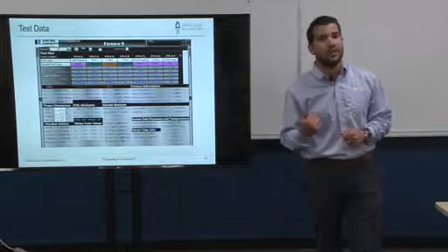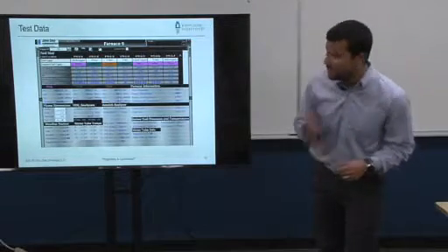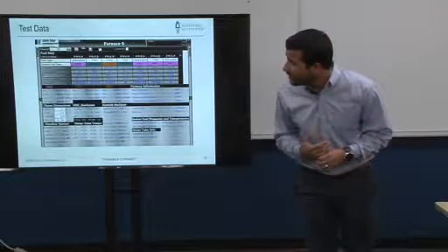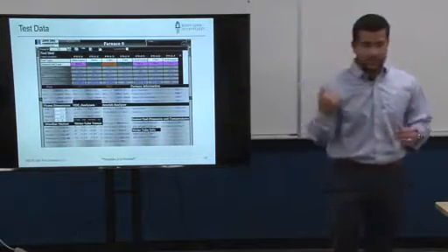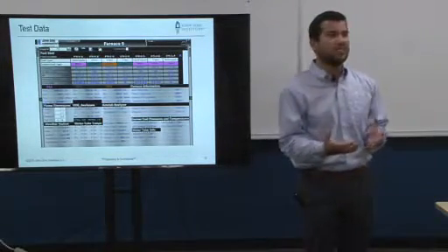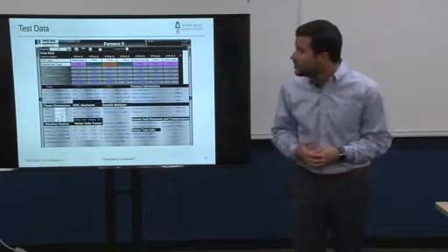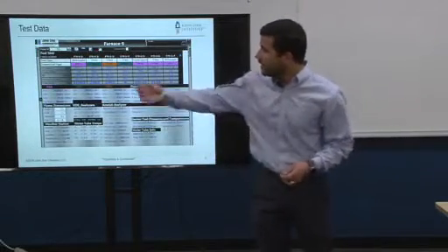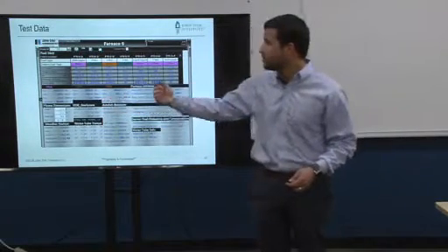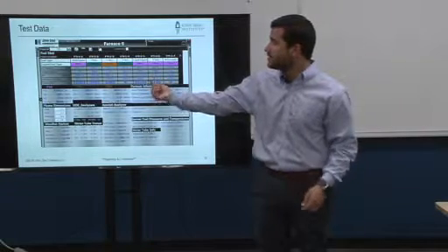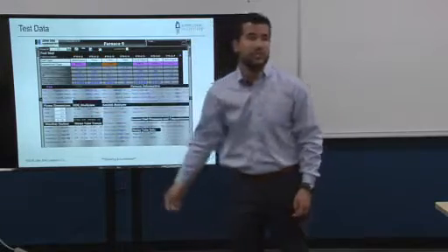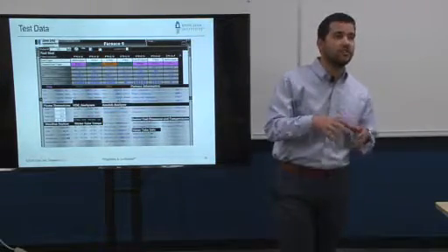So this is, I'm pretty sure I did this test. This is a downfire reformer, and actually using turbine exhaust gas too. So it's a downfire reformer where you have a main fuel that is your RFG, which stands for refinery fuel gas, okay? You can see that the RFG is firing about 2.44 million BTUs an hour, and in addition to that, there's a PSA that is made out of hydrogen, natural gas, and nitrogen, that is firing about 5.73 million BTUs an hour. So those are on the main burner.